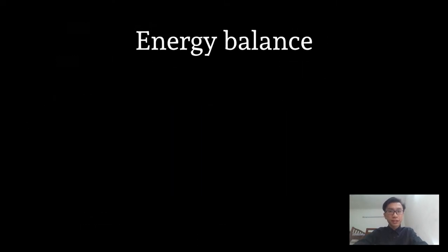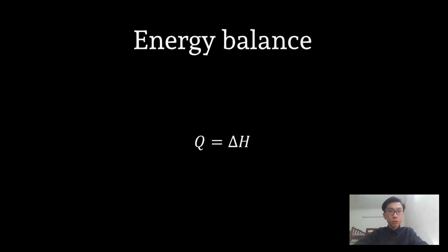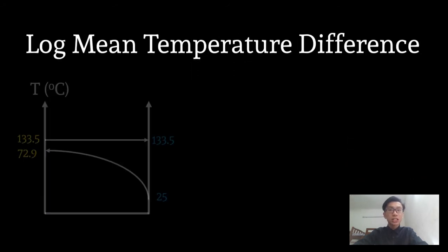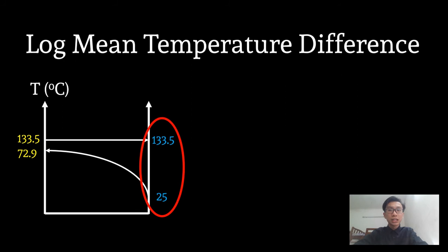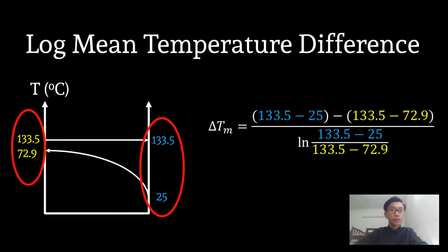In order to justify the answer, first we need to calculate the heat transfer from steam to streamline. At heat exchanger, there is no work done. Thus, the relationship between enthalpy and heat is equal. So, we get the heat absorbed by the stream, then we calculate the LMTD. But first, what is LMTD? LMTD is log mean temperature difference, which is the temperature difference at one end between heat exchanger and stream with the other end divided by natural log of the ratio of these two temperature differences.